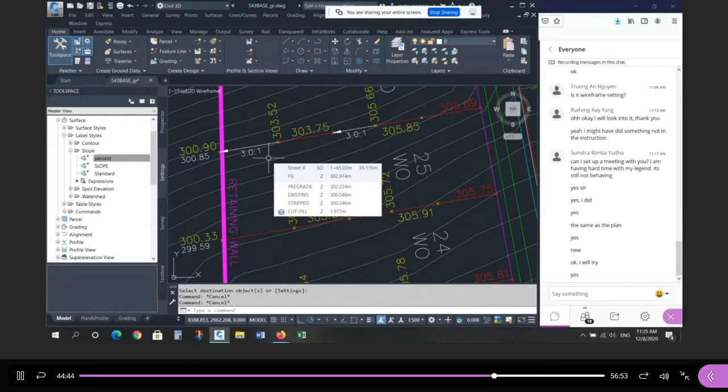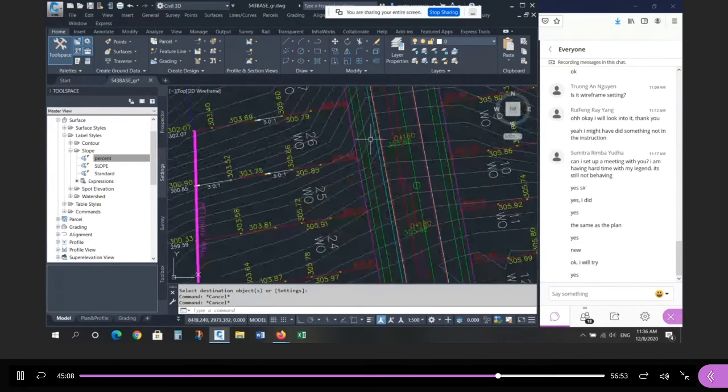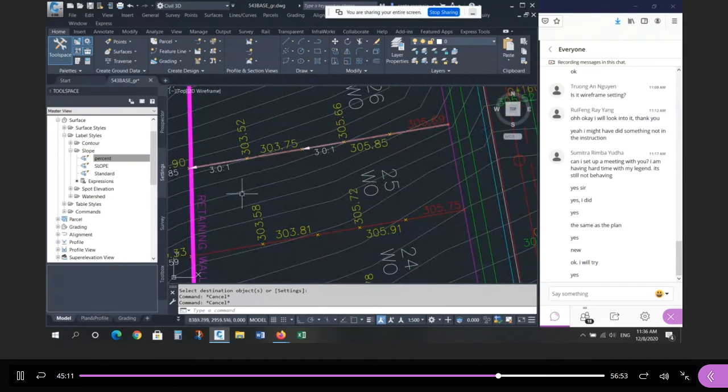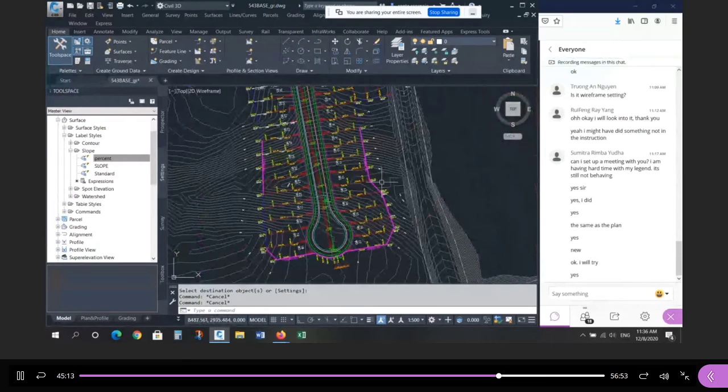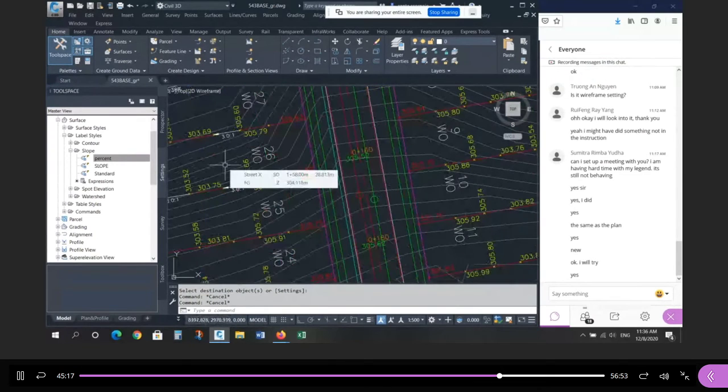I didn't ask you to do that. I didn't ask you to show the slopes along the lot lines, but on a lot of drawings, you would have to show that. So there's a little tip and trick. Okay. If you're creating a portfolio, you might want to add that. If you have time over the break, you want to add that detail to the grading plan. This is a grading thing. Then I would take the time to do that. And it's mundane, it's tedious, but you got to put it in. If it's a walkout, you might need 1, 2, 3, 4, 5 labels on every lot line. It's a lot of work, right? But it conveys your design a lot better, and it's something that most municipalities require. They want to see the slope between the 2 points.